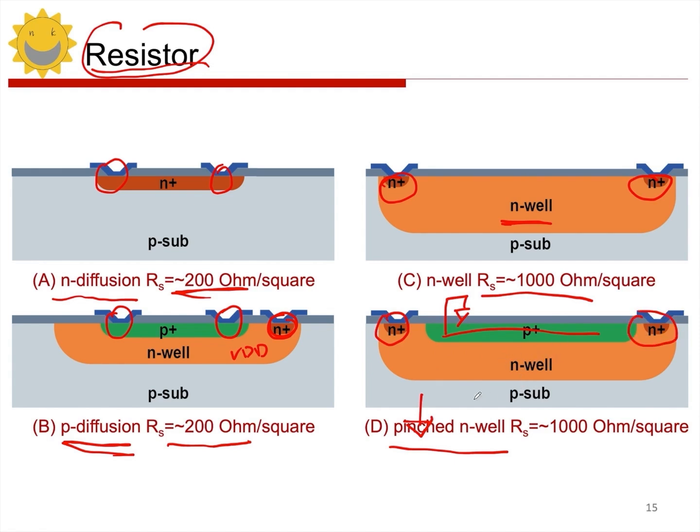Now, what's the purpose of doing this? Why do I want to create a heavily doped layer of N-type material on the surface of this N-well? The main issue is that, let's take a look at the scene above. The surface of this N-well is actually the surface of the wafer, right? And on top of that, there's silicon dioxide. So, in this way, the surface of the N-well has a broken lattice, right?